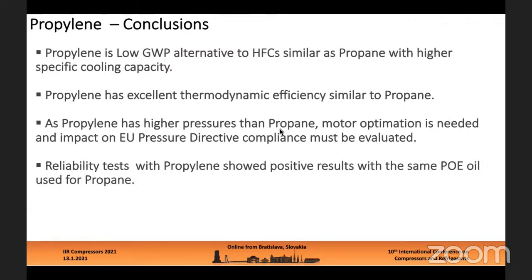Propylene has higher pressures, so the motor needs to be optimized, and compliance with the pressure directive in Europe needs to be evaluated. Reliability tests show good results with the same oil as is used for propane or 404A.